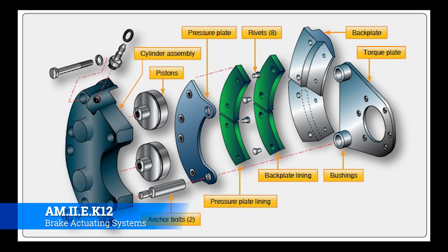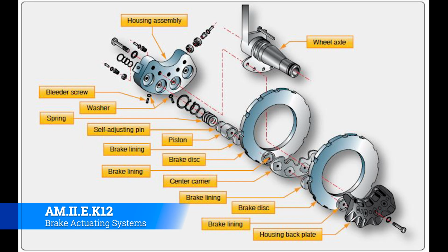Pretty simple system, very versatile, very widely used in general aviation. Okay, stepping up a little bit in the complexity is dual disc brakes. Now, these get used whenever one single braking disc doesn't supply enough friction.